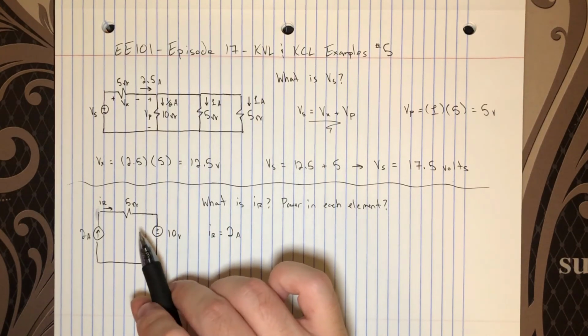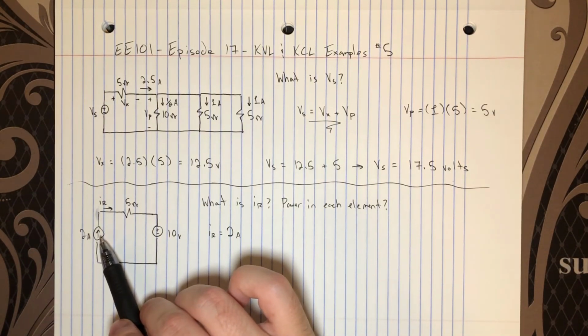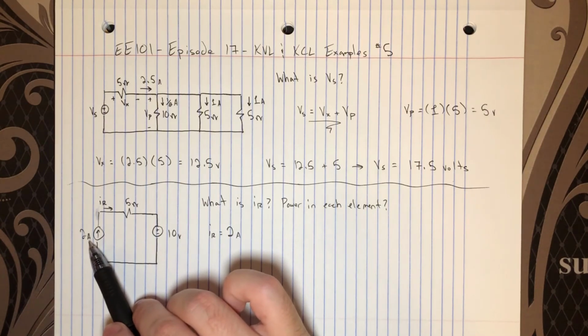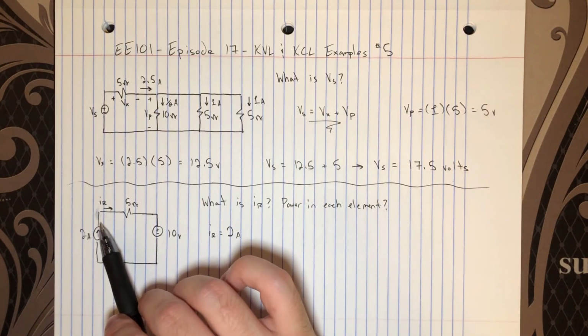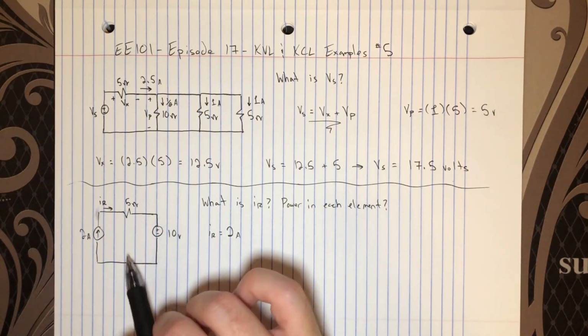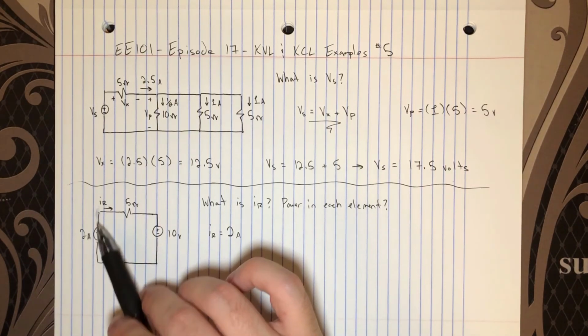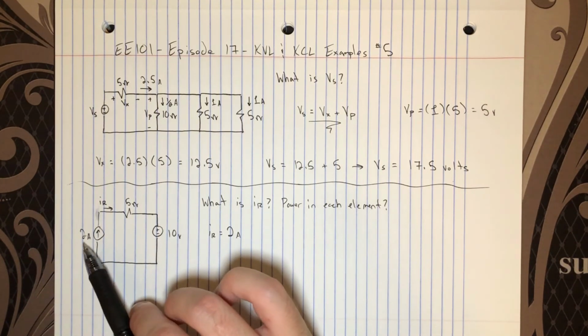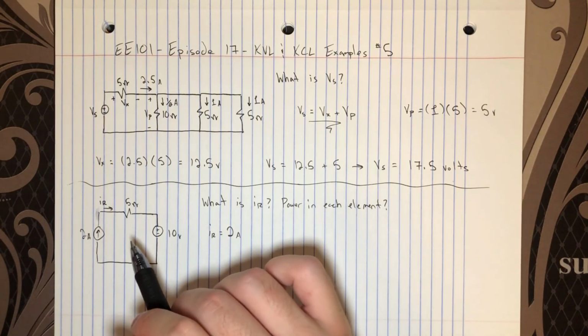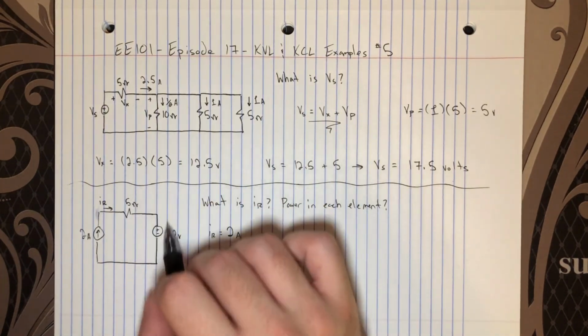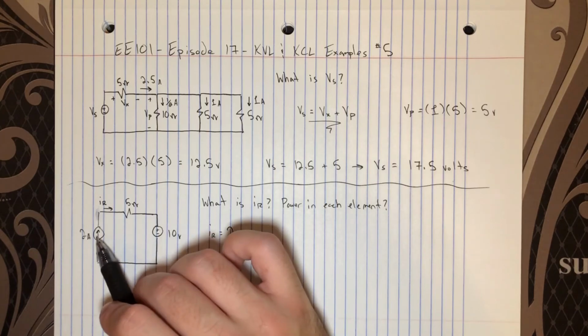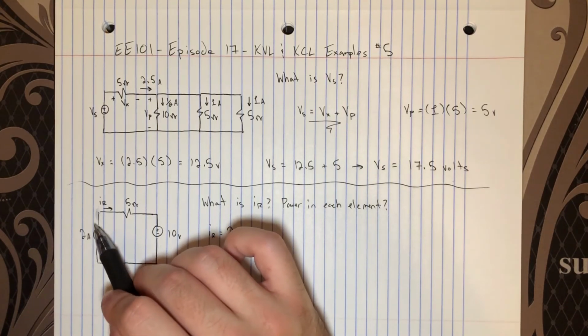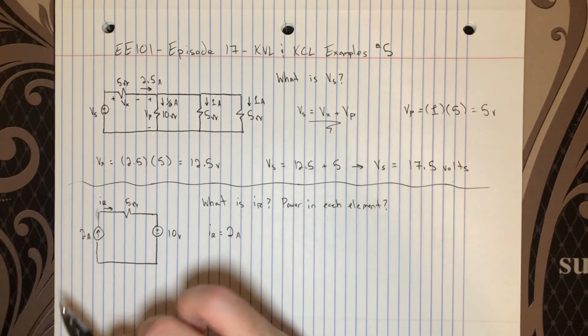Depending on what you attach to that voltage source, there will be a different current, but the voltage won't change. This current source, on the other hand, forces a specified current to flow. Usually, depending on what current flows, it'll interact with the circuit and cause some voltage to appear across it, but this current shouldn't change. So again, it doesn't matter about all this other stuff. This IR is just 2 amps. That's what's being forced out of this ideal current source.